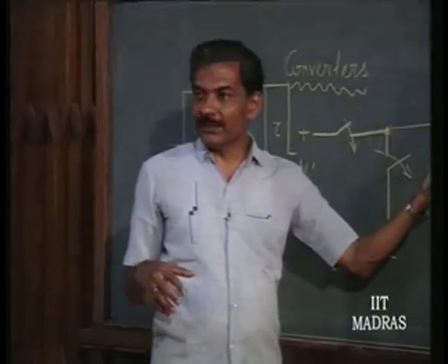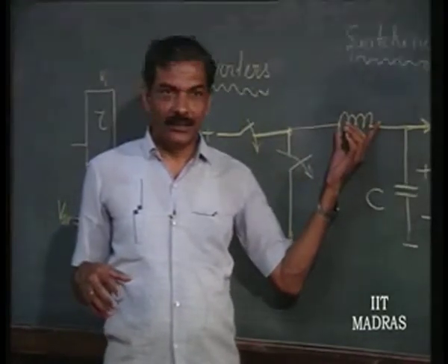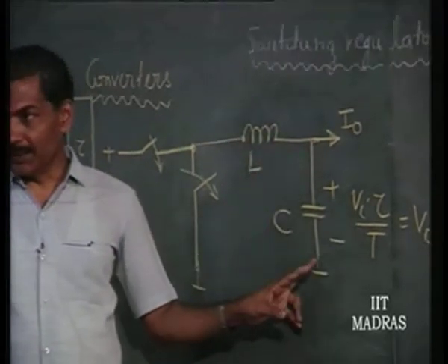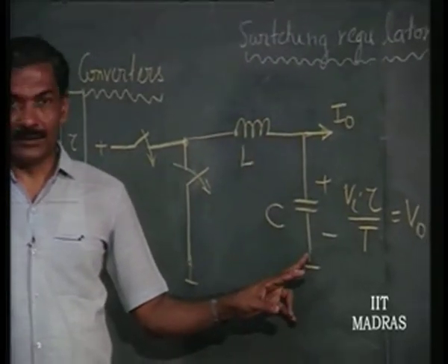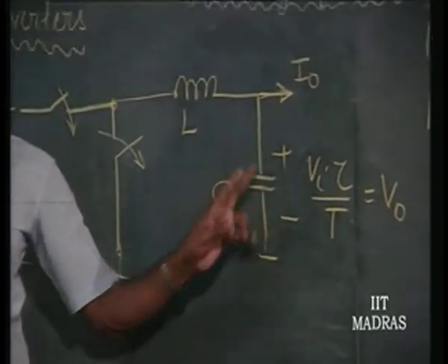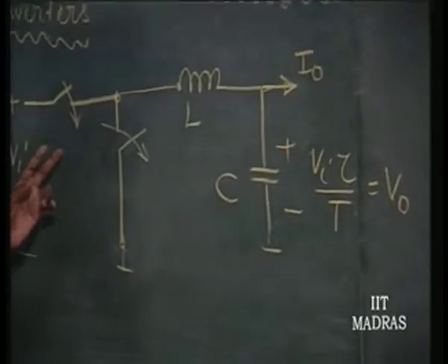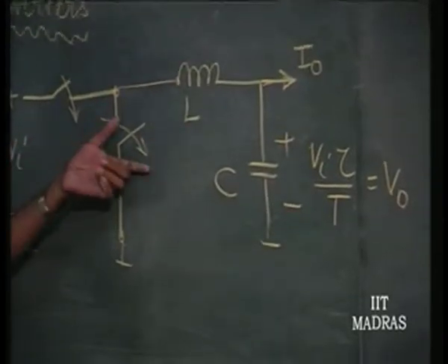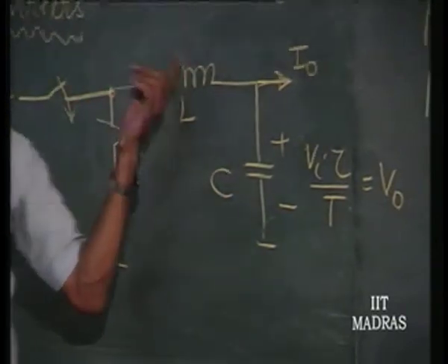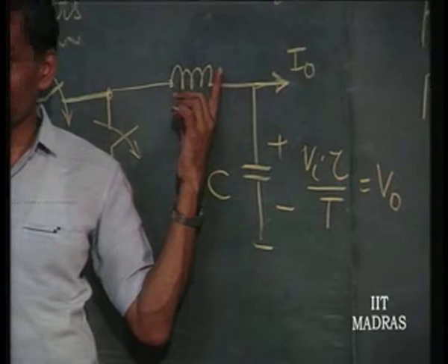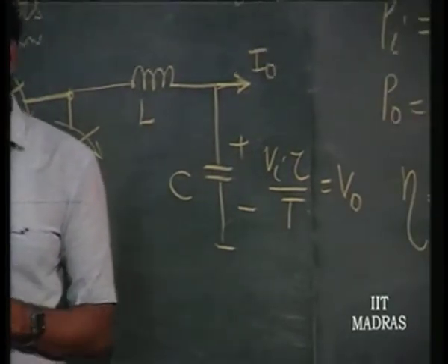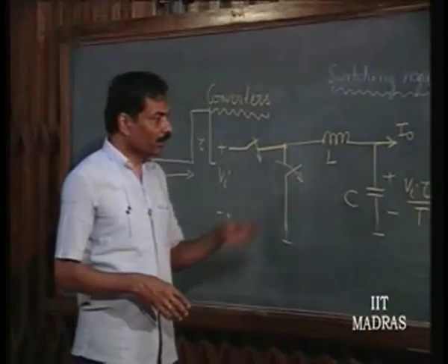There is going to be some DC resistance or AC resistance here, which is going to cause a certain amount of power dissipation. There is going to be here a leakage resistance, which is also responsible for a certain amount of power dissipation. The primary power dissipation in switched power regulators occurs in the switches when they are on, and in the inductor because of its finite resistance. The rest of the power dissipations are negligible, components are small. Now how do we analyze this?